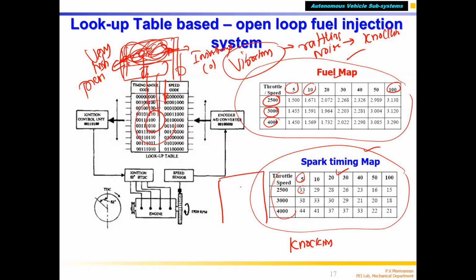As I told you, this is your piston, and you have a spark plug. When the spark is given, first the air fuel burns here. From here, layer by layer, the fuel starts burning. This is called the flame front. The flame front starts moving from this place outward, so the fuel air is burning in an orderly manner. In good combustion, the petrol air mixture starts burning at one place and the flame moves on in an orderly manner, so the pressure also increases linearly, correct?